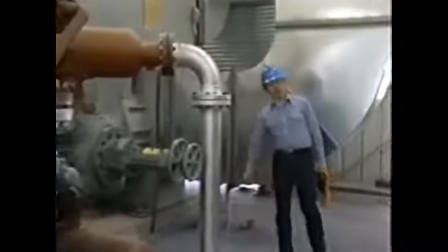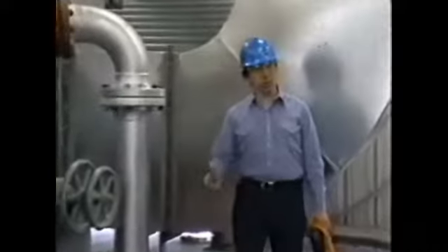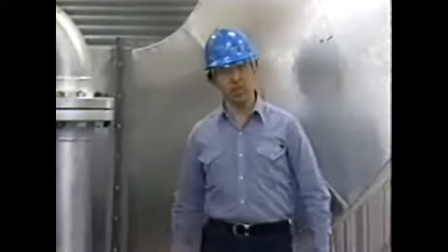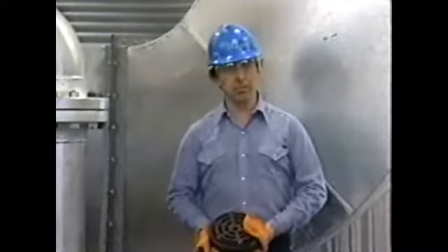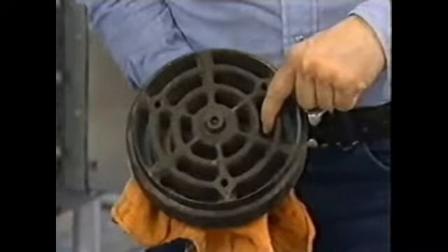Various types of valves are used in compressors. A typical valve for a heavy-duty reciprocating compressor, such as this, is the plate valve. In a plate valve, the part which closes against the valve seat is a flat metal plate. These plates are held against the seat by a set of springs. Before we discuss the operation of valves, both suction and discharge, there's a very important point that needs to be understood. Both suction and discharge valves are identical pieces of equipment. Their function as suction or discharge valves depends solely on their placement within the cylinder.